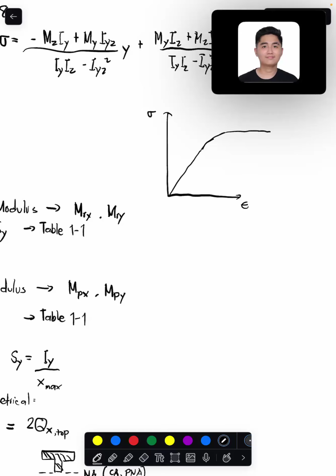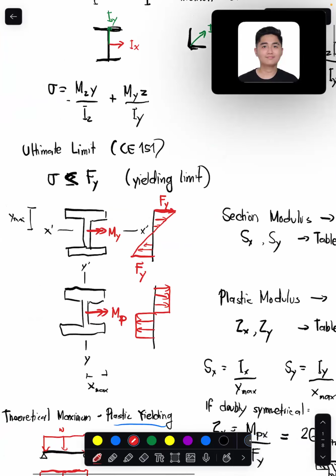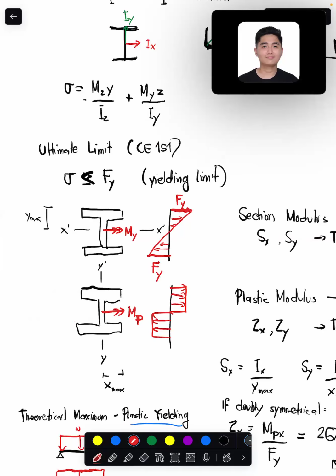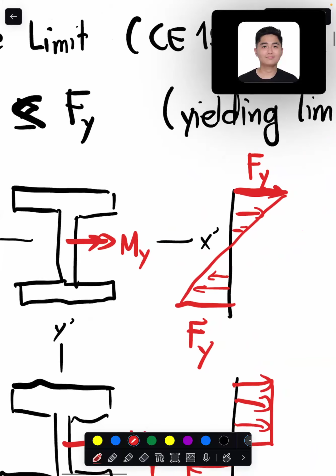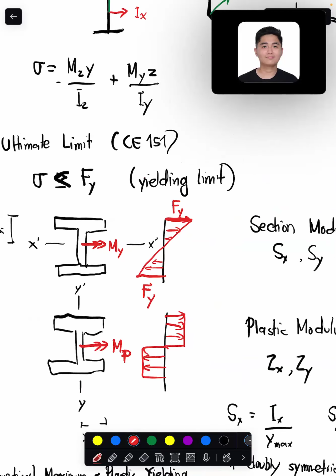what do we consider? So to recap again, what do we consider? Remember that instead of E, what you consider as the modulus of elasticity is the tangent modulus. So essentially, this part is where you identify what's called the residual moment. The residual moment is just saying that it will no longer reach this. It will no longer reach this. The onset will come earlier. How does the onset come earlier?